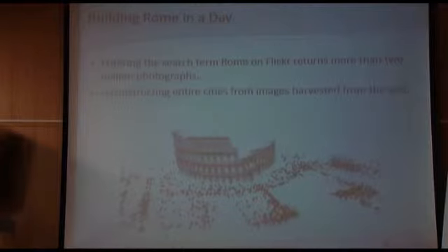The question is why? Why is there always holes? The answer is quite easy. Because if you have a structure where there are no features on it, so it means like white boards, here you have structure, but if you have a plane where there are no features on it, it's not possible to compute the correct position, and that's why the model here would have holes.